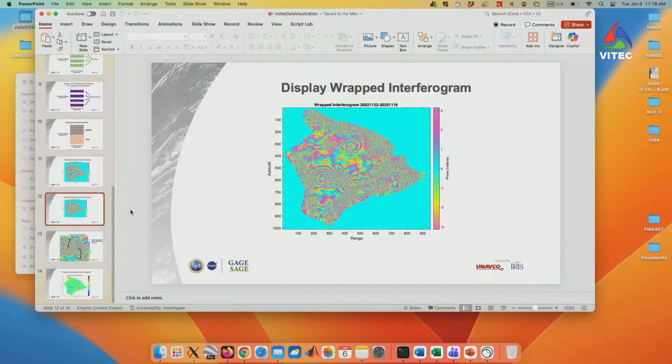And here are some topographic anomalies again. And here is a close look. What you can also see in this image is that the ocean area was clipped, right? In our original data, we didn't clip it. The way to generate an ocean mask is actually fairly easy. If you think of the amplitude image, the amplitude of the ocean is pretty low, right? So you could use the amplitude image to derive a water mask directly. That's usually how we did that.